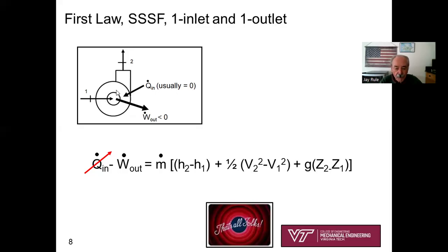There may be some vertical pipe that's connected to the pump, and for some reason you've been given, say, the pressure up at state 2 at a very, very high location. And you would draw your control surface from state 1, the inlet of the pump, all the way up high to state 2. You see that in that case, your potential energy change term would come into play if you were drawing your control surface way up high and included a very tall pipe.